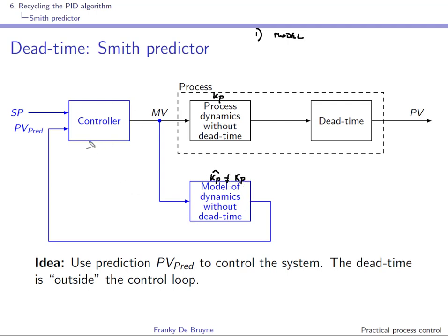So if we have here a controller with integral action, the predicted PV will be on set point in steady state. But since the gains are different here, the PV is going to be different from the predicted PV in steady state, so it's not going to be on set point and will have a non-zero steady state error, right?